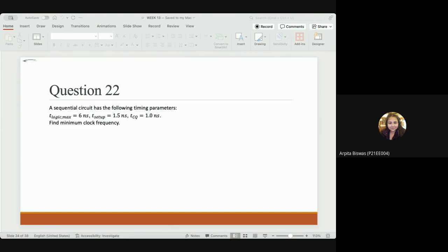In atmospheric pressure CVD, it takes more than 50 to 60 runs. One run needs 8 to 9 hours. So you can think how much time it takes when you're optimizing one material parameter. Then you fabricate, and you don't know, you have the idea that it may work, but you have to do all the optimization. Then we have to fabricate the device, and all these things you have to do on your own.